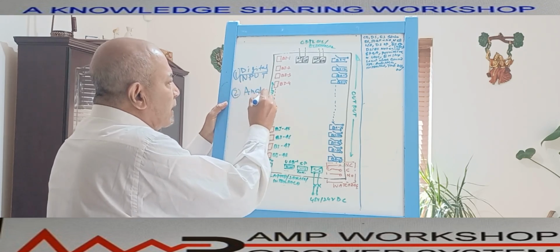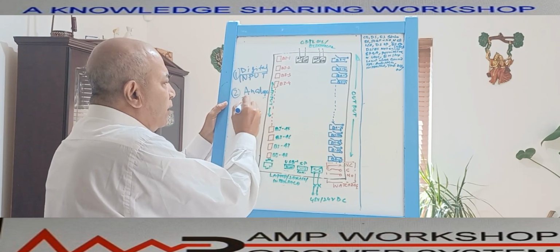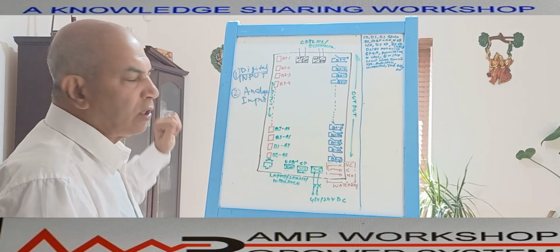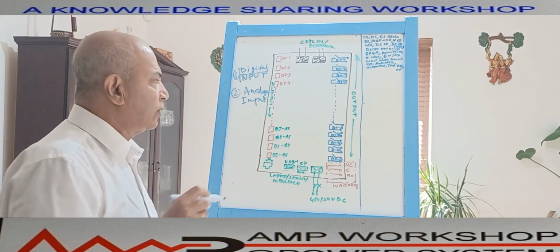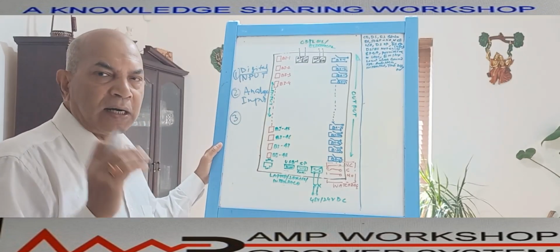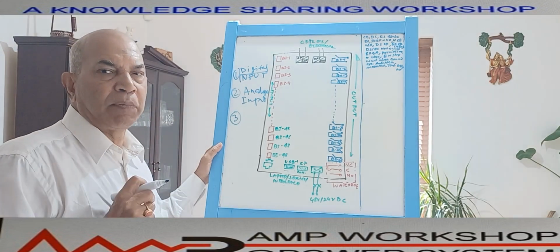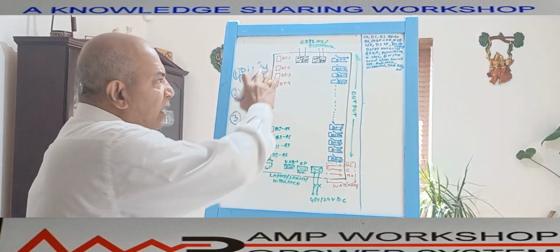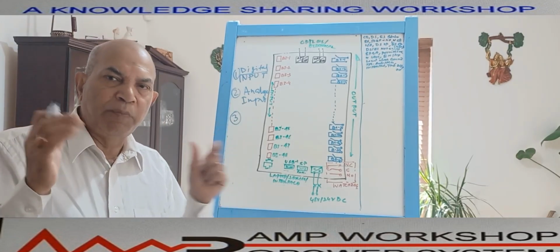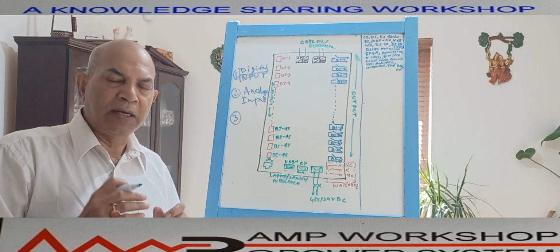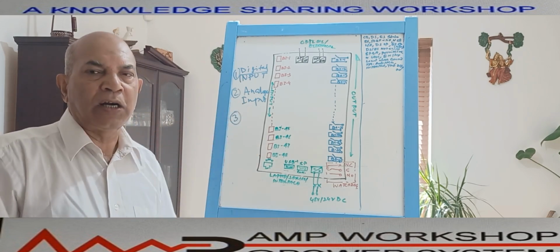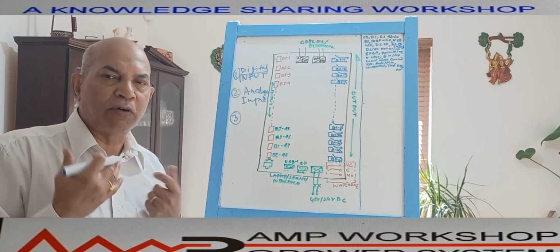That is the second part, it can do analog input. These are, from the input point of view, the two things it can take, as well as number 3, another analog signal, that is the DC control supply to the relay, because this relay, nowadays an intelligent relay, is a small computer. It is another computer and it has more capability than a computer. So to operate this internal system including software, it needs a control supply.